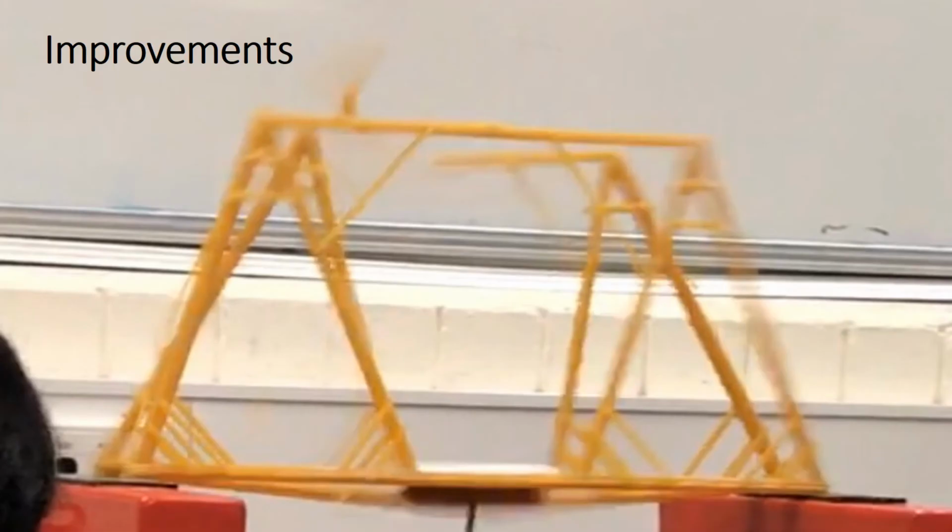The top cross member was the first point of failure. Due to weight restrictions, we could not thicken this member as much as we would have liked to. Building a thinner base would have allowed for a thicker top cross member. Although the truss calculations showed the base was under minimal tension in comparison to other members, we still built a thick base. This was due to concerns of supporting the weight plate.